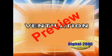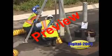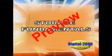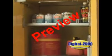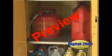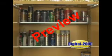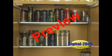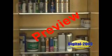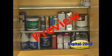Ventilation. Always provide adequate ventilation to reduce the potential for ignition of flammable vapors. Storage fundamentals. Storage fundamentals identify incompatible chemicals. Check the material safety data sheet. Isolate and separate incompatible materials. Isolate by storing in another area or room. Degree of isolation depends on quantities, chemical properties, and packaging. Separate by storing in the same area or room, but apart from each other.